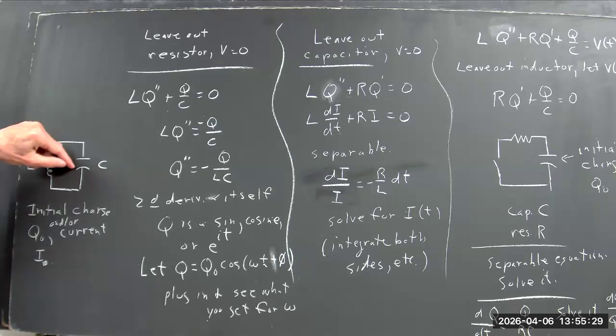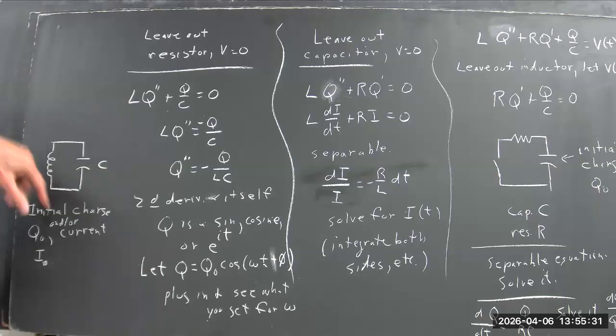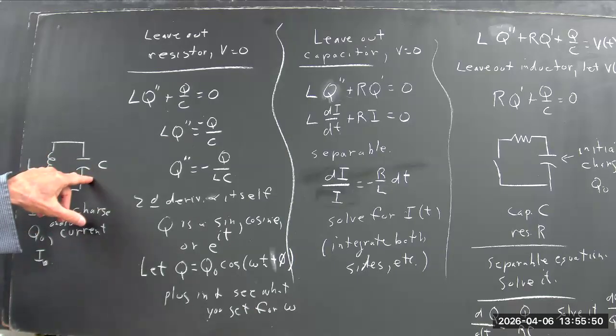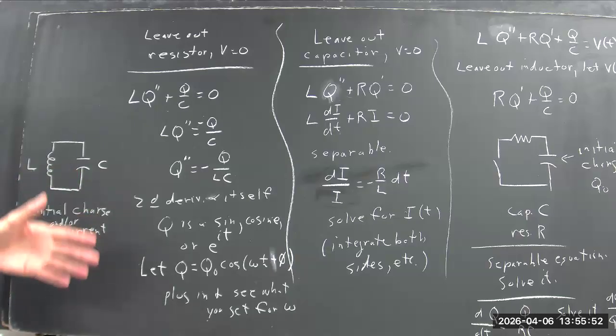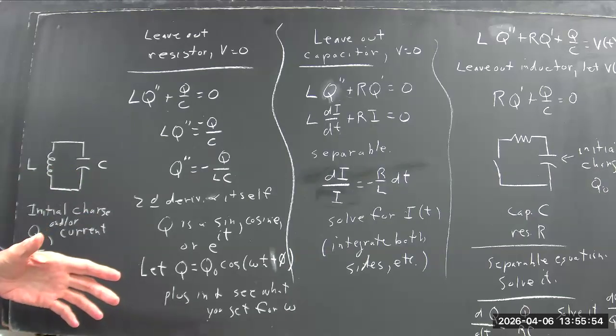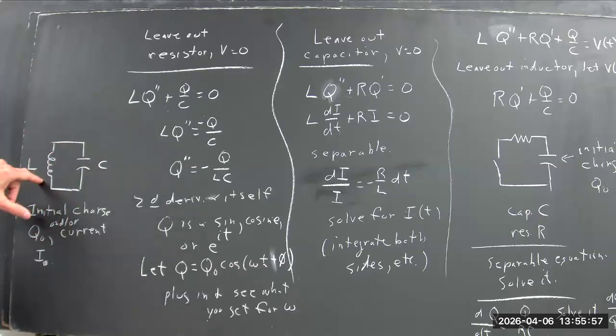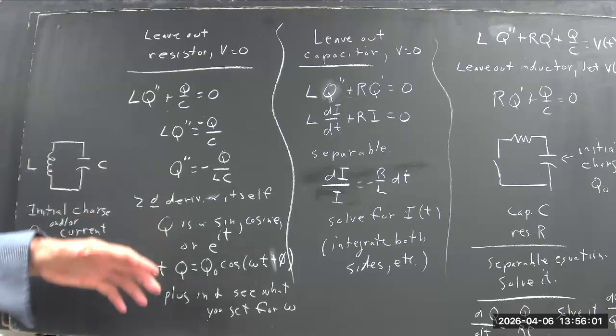And then the capacitor eventually gets rid of all its charge, and now the inductor has all this current running through it. It can't drop to zero instantly. So the current keeps going, it starts decreasing, but that charges the capacitor up again. And then it all starts over. The capacitor gets completely charged, the inductor gets rid of its current, and now the capacitor charges up the inductor again, which in turn then charges the capacitor.